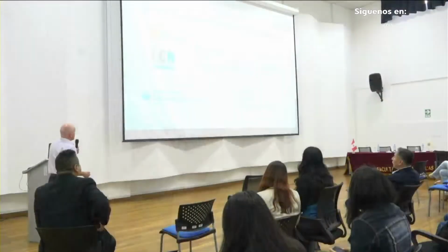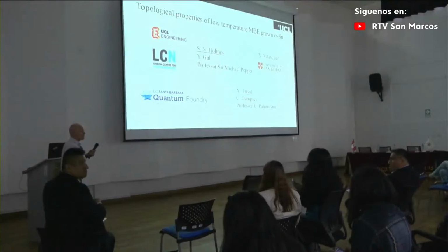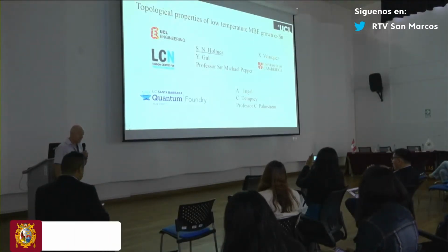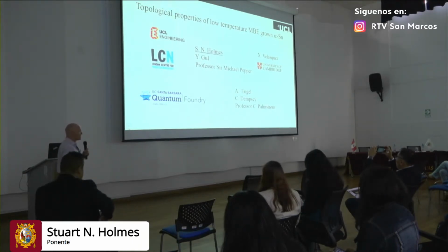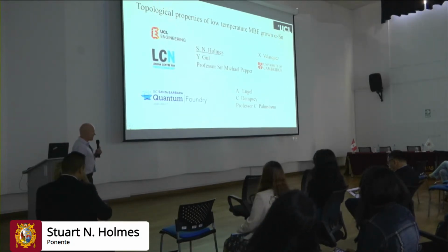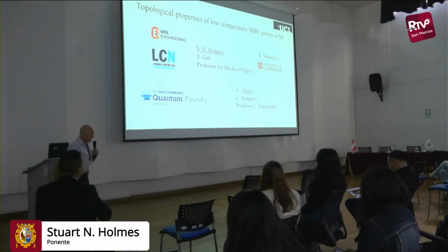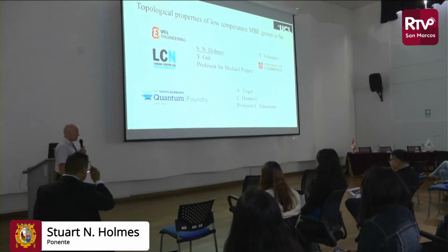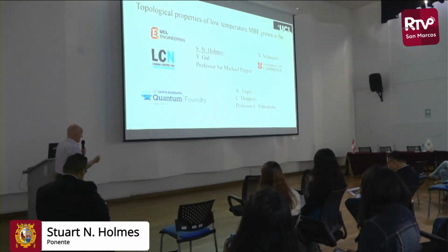So I'm here today to tell you about the fantastic properties of alpha tin. Alpha tin is a different form of tin. It's a semiconducting form of tin. Normally, when we think of tin, the element tin, we think of it as metallic and superconducting. But if it's grown in a low temperature phase, it's stable in the alpha phase, which is a narrow bandgap semiconductor. So I'm going to tell you about some electrical measurements today.